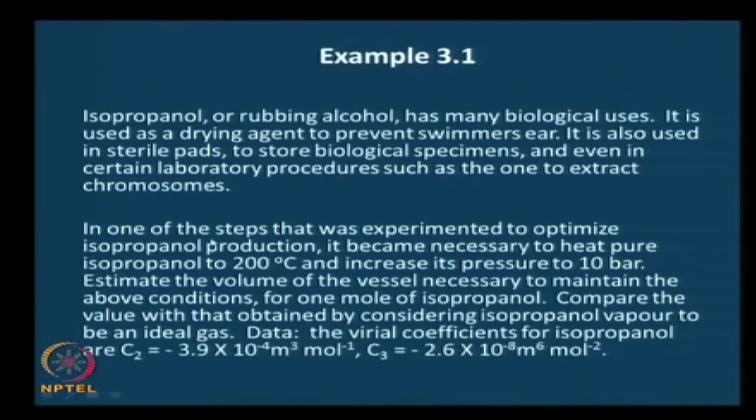And the first improvement that we saw was the virial equation of state, which we said could be written either in terms of a series in pressure or a series in specific volume. Then we had posed this problem to become comfortable with the use of a virial equation, and had given you some hints and an initial part of the solution. So let me present the complete solution here.